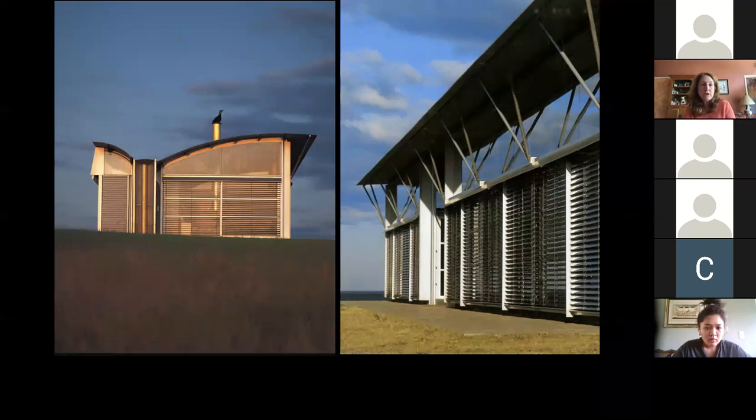And I want you to notice on the upper part, I think you can see my cursor there, that this upper part of the wall is slanted out. And what that does is it allows this little horizontal lip here. And that enabled not only these larger windows to open on the angled wall, but in that little horizontal lip, it allows for these horizontal vents to be able to help facilitate ventilation.